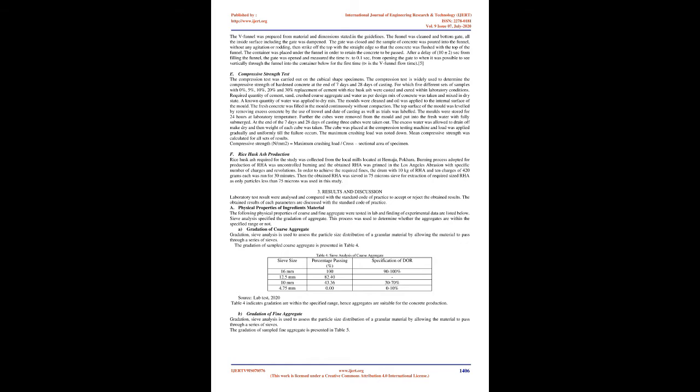and then the gate was raised so that the concrete flows into the horizontal section of the box. When movement ceased, the vertical distance was measured at the end of the horizontal section of the L-box, between the top of the concrete and the top of the horizontal section of the box, at 3 positions equally spaced across the width of the box. By difference with the height of the horizontal section of the box, these 3 measurements were used to calculate the mean depth of concrete as h2 mm. The same procedure was used to calculate the depth of concrete immediately behind the gate as h1 mm.